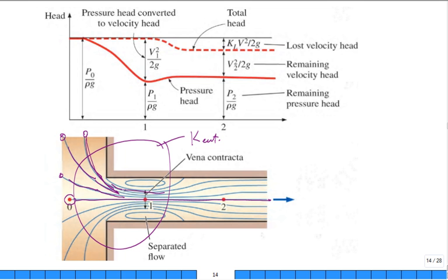And what will happen is it'll lead to a region of, what's that? It's a recirculation region. It's separated flow. The flow is separated. It gets attached back here, and now it's flowing all downstream. But in that region, there's little zones of recirculating fluid. It's actually as if there's a contraction in the entrance region. And so you get an energy loss due to the flow.